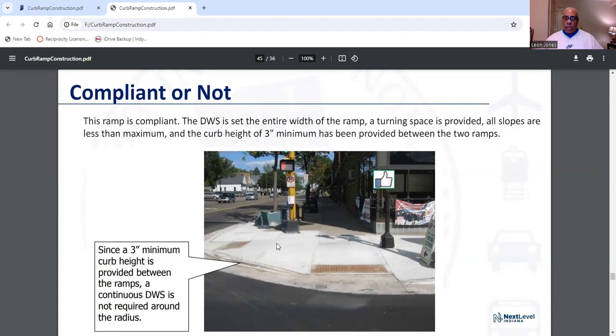Remember, when you place these ramps at corners, you must also provide for the drainage, because you don't want ponding on these ramps. One thing you must understand with construction, period: where is the water going to go? You have to understand the slopes. Water does travel fast, so that's why 2% is required. Generally, your roads have 2% slope from the crown.